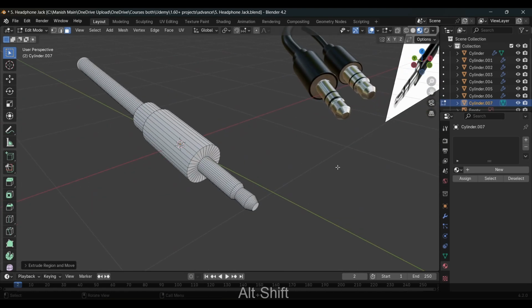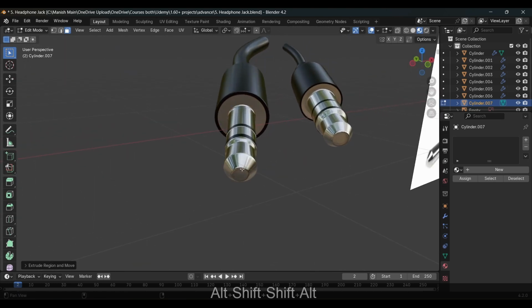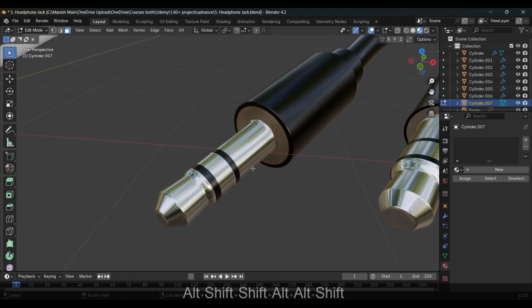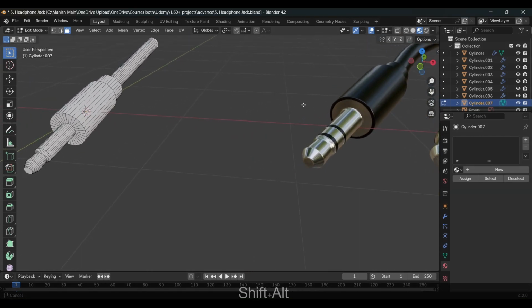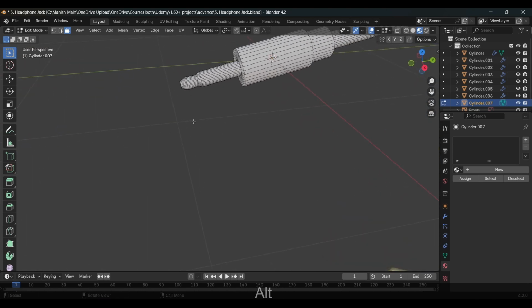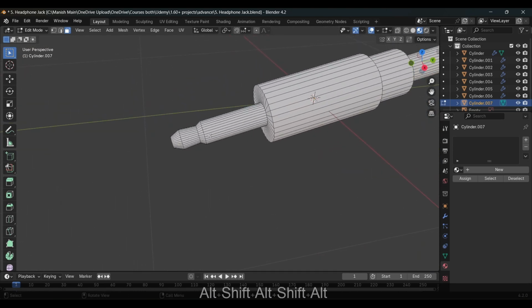Now we will texture it, but here you can see this material is black in color first. Notice this material is also black in color second, and from this and upward this material is also black in color, third. So basically we need to separate 1, 2 and 3 by pressing P or by adding a loop cut on our mesh. So firstly we need to add a black portion here. So firstly I'm going to add a loop cut here. So I'm going to press Ctrl R and add a loop cut here, and press Ctrl R again for another loop cut.